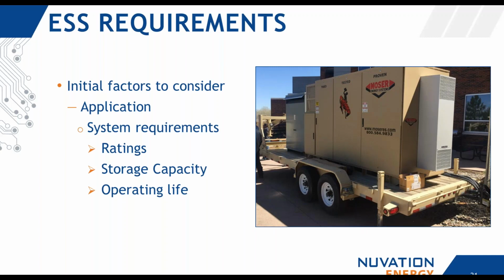And what they use this for is peak shaving and voltage and frequency stability at the site. By combining this battery with the genset, they were able to halve the amount of fuel consumption by the genset, and they were able to double the life of the generator. So this is a very economical investment in battery technology to improve the capabilities of this application.